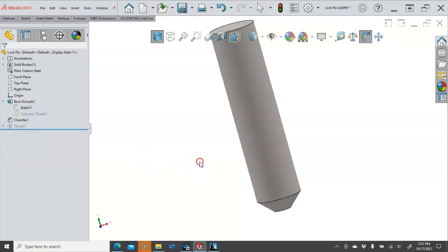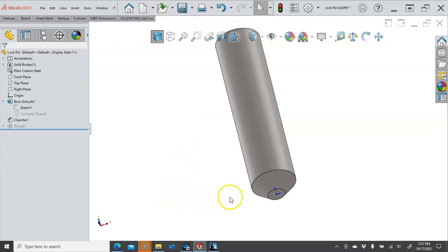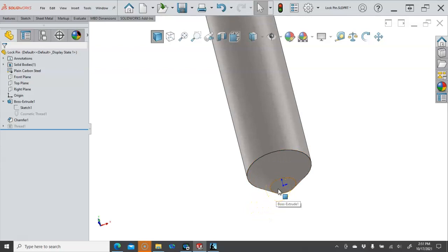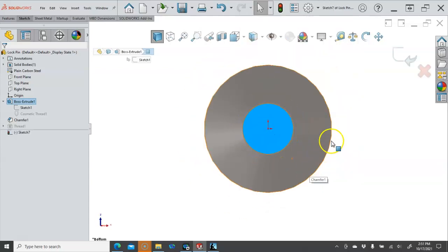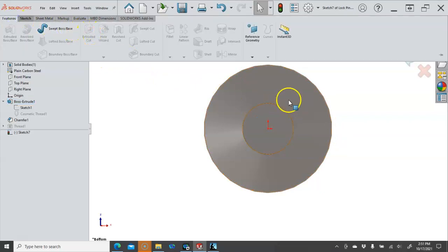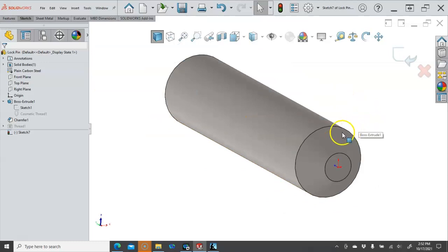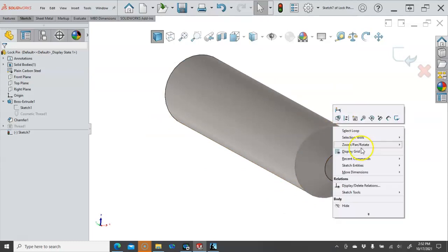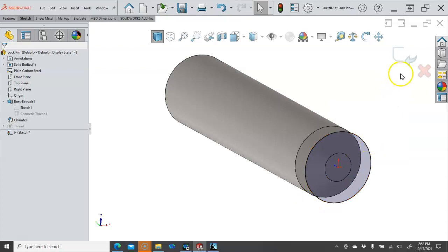If I suppress that one, then there is the traditional cut swept, where we end up drawing the geometry. So if I go in and create a sketch, a sweep is 2 parts, and this is going to be a little more complicated. So I want to just start on the end face and convert. I missed it, so let's see if it's popping up there. Sketch tools, convert entities. All right, so that'll work.